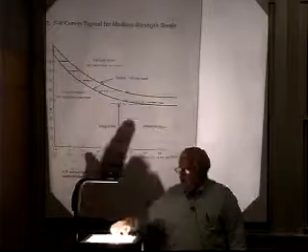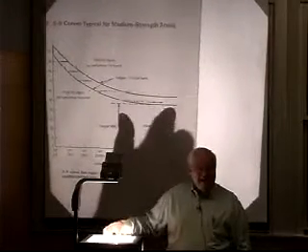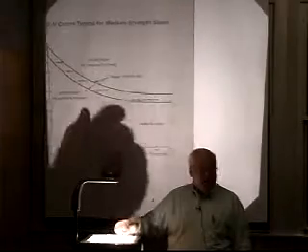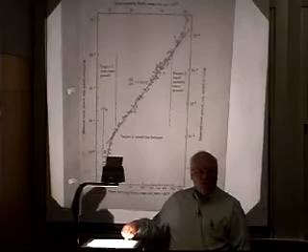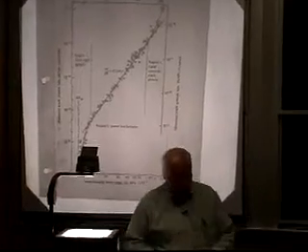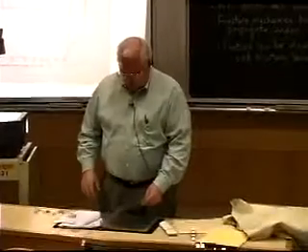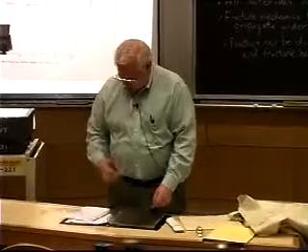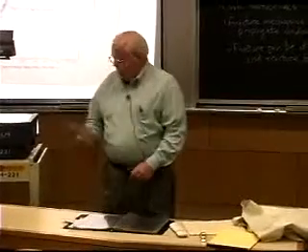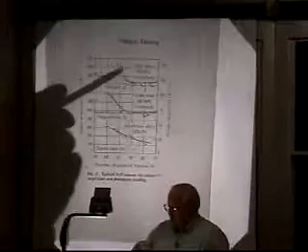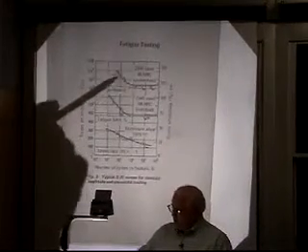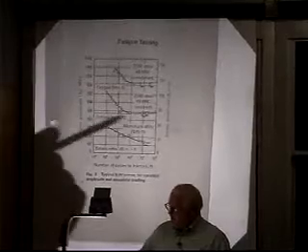Not very big flaws, but basically if you went and put that typical flaw size in and then calculated that stress and the stress intensity, you would find that you were at what's called the threshold stress. The threshold stress, where you don't have enough energy input per cycle at stress intensity to do damage at the head of the crack. In the old days, with the old type of SN testing, if you did a particular steel at a particular hardness in an unnotched condition, you get this stress. If you did it in a notched condition with a stress concentration, you get a lower curve.